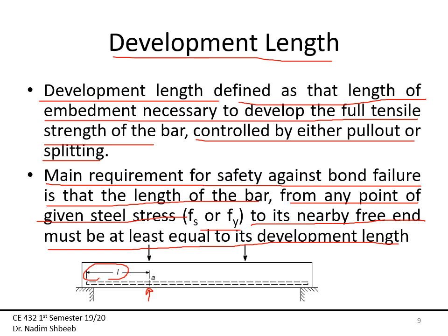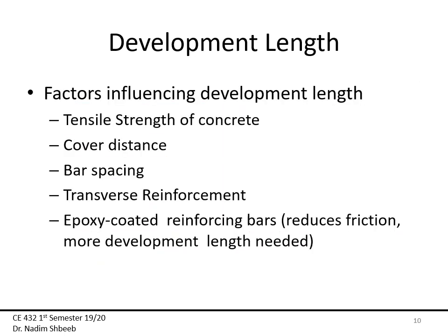So instead of worrying about what the actual bearing, splitting or slipping stresses are, we said, what is the adequate length required for me to get to that perfect bond? This is what we will attempt to do. So at least now when I talk about development length, you will know why I'm talking about it and why I'm going to stop talking about both the splitting stress and the bearing stress. It's how I converted that concept into this concept.